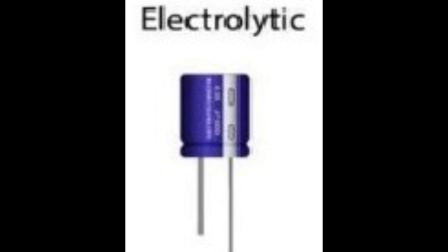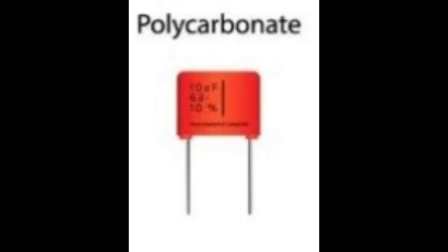Because of its potential for large capacitance, this type of capacitor is used extensively in power supply circuits and similar applications. Polycarbonates are a group of thermoplastic polymers which find uses in many areas of industry as they are easily molded and thermoformed. They also possess a number of useful features in that they are temperature-resistant and impact-resistant. Polycarbonate is also used in capacitors as a dielectric.